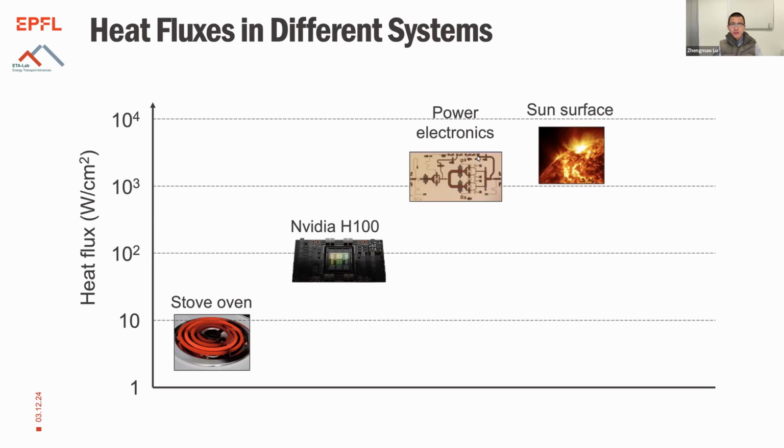For a heat transfer system, there are usually two things that you care about. One is the maximum capacity, the maximum heat flux this cooling system can deal with. If you receive a high heat flux, is your cooling system going to fail? This is more important for the power electronics, where the heat flux dissipation requirement is more extreme. People have been pushing the cooling performance to take care of the higher heat flux, like above 1 kilowatt per centimeter squared. So that's one important metric.